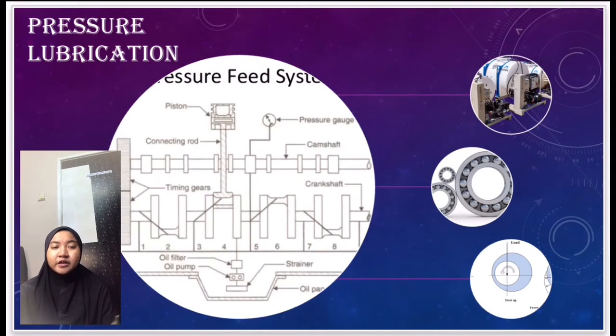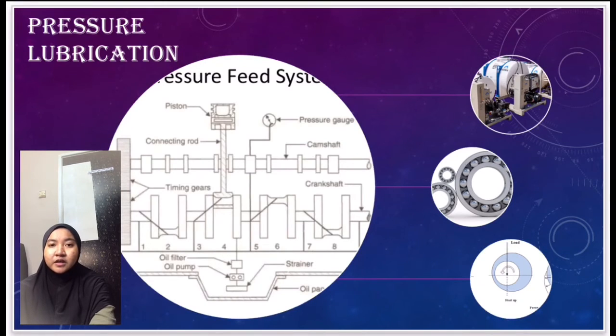Four is pressure lubrication. For high-speed and high-power machines, a loss of lubricant can result in rapid bearing heating and damage due to friction. Also, in dirty environments, the oil can become contaminated with dust or debris that increases friction. In this application, a fresh supply of lubricant can be continuously supplied, and complete internal combustion engines use it in parts of the engine where directly splashed oil cannot reach, such as up into the overhead valves especially. High-speed turbochargers also typically require a pressurized oil system to cool the bearings and keep them from burning up due to the heat from the turbine.